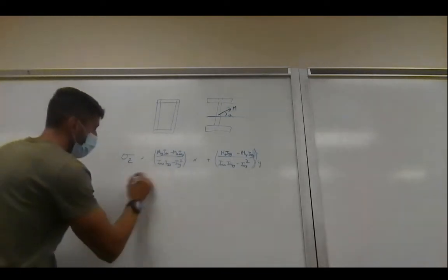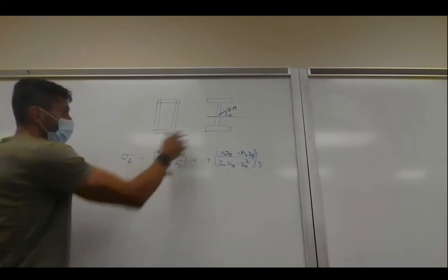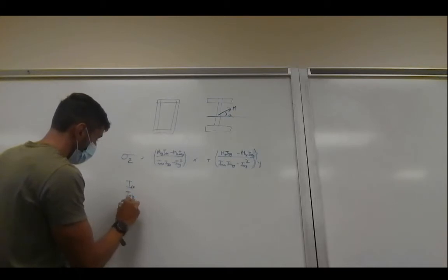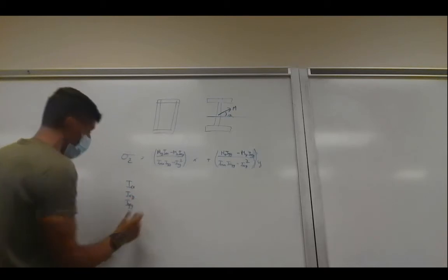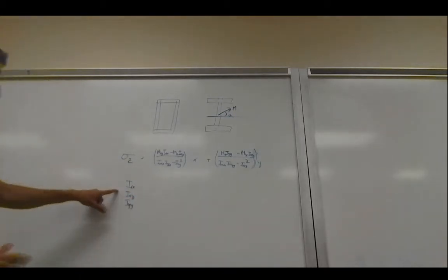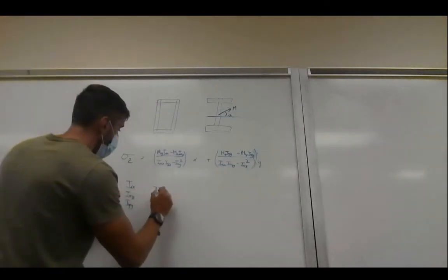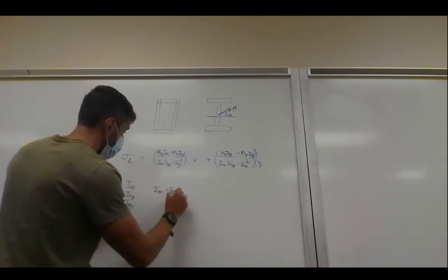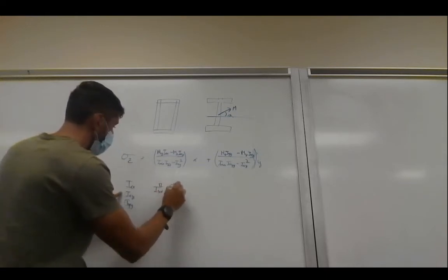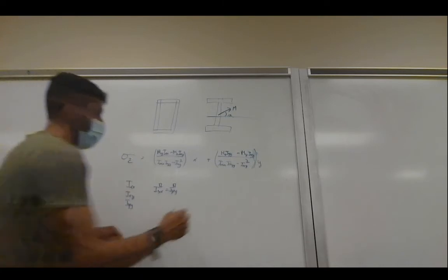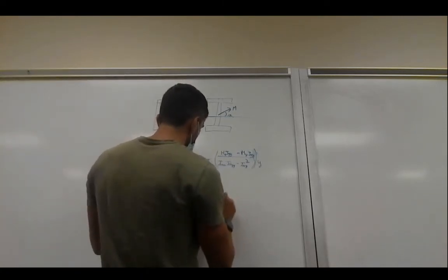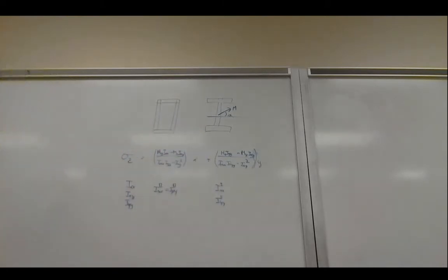The question you had to do is, first of all, find the moment of inertia. For the square, you can say Ixx is equal to Iyy, so you have to find only one for the square. Ixy is equal to 0 because you have symmetry here again, and you have Ixx of the I-beam, and it's different from the Iyy because it's not doubly symmetric.